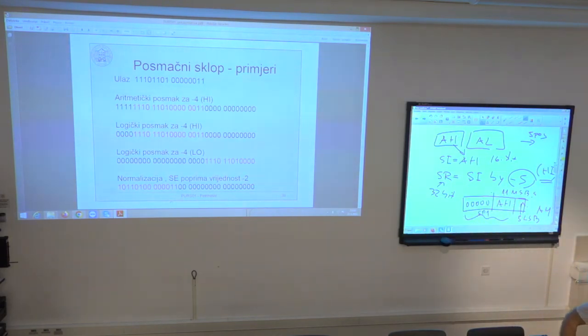A negative value that is greater in magnitude than 1/2, so less than 1/2 negative, would always have 1, 0, something. If I have 1, 1, something, it means it is negative, but in magnitude less than 1/2. So I could shift it to the left at least by 1 position, because it is not normalized.